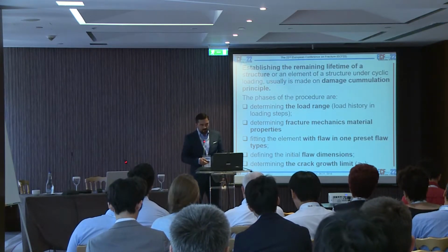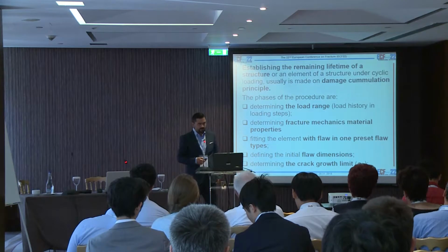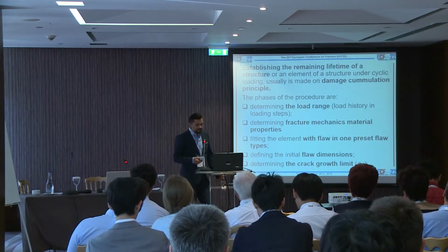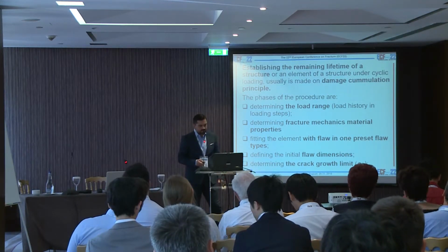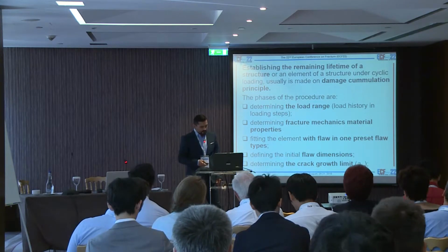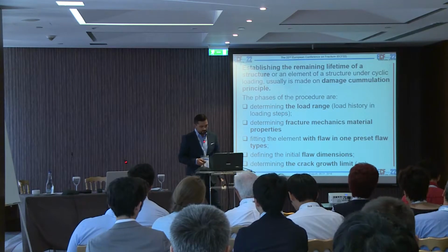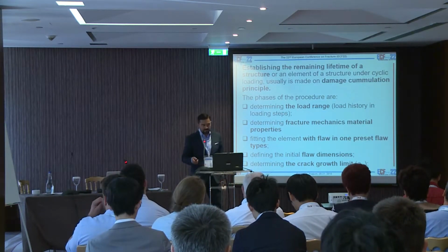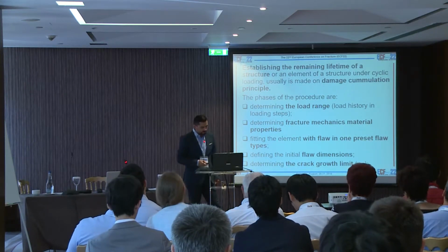It also establishes the remaining lifetime of a structure or an element of a structure under cyclic loading, for which, of course, as we all know, a damage accumulation principle is applied. As phases, we need to know the load range. That's maybe a problem we'll see afterwards. Then determining the fracture material properties, and fitting the element with the flaw into one of the preset flaw types. Defining the initial flaw dimension is another problem.